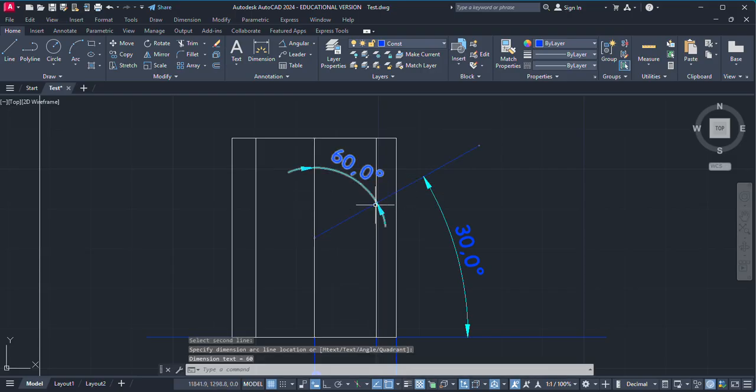We need to draw this line such that it makes an angle of 60 degrees with the axis, and this line is bisecting the axis, meaning it is passing through the midpoint. So this axis is divided into two equal parts. Now just remove this angle here. Now you can remove this axis line. Select this, and move it to the main drawing.